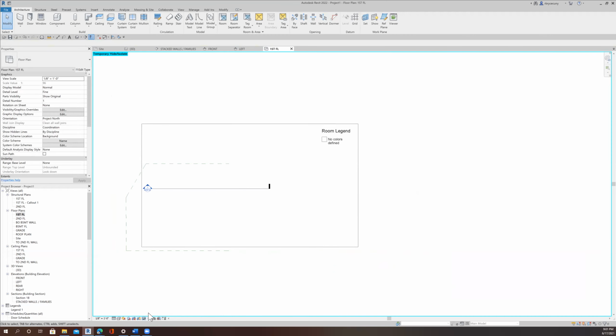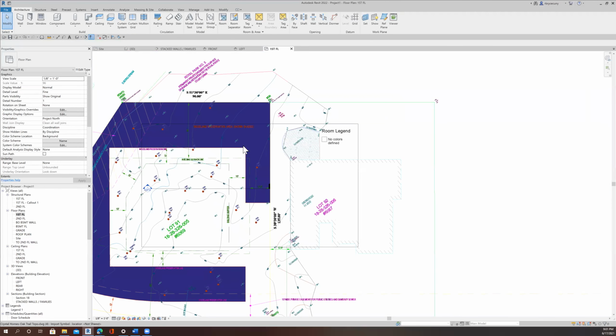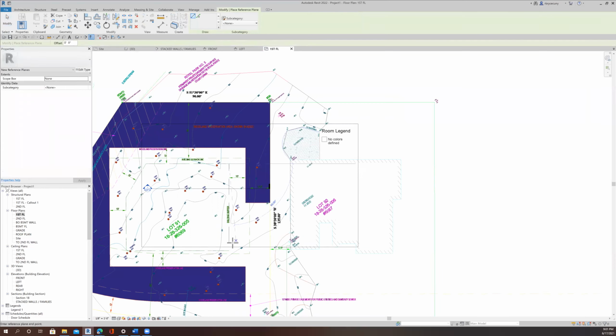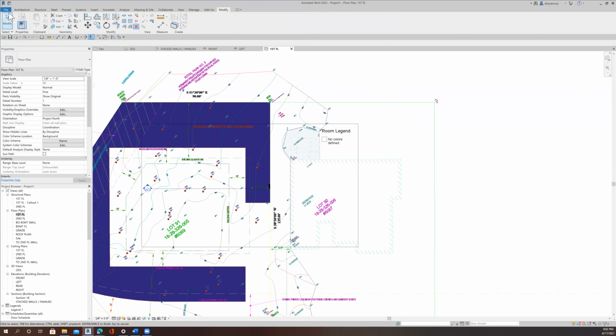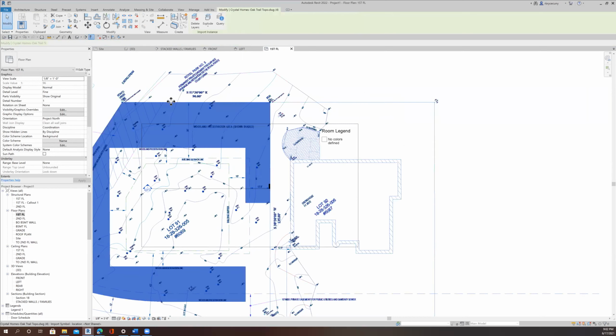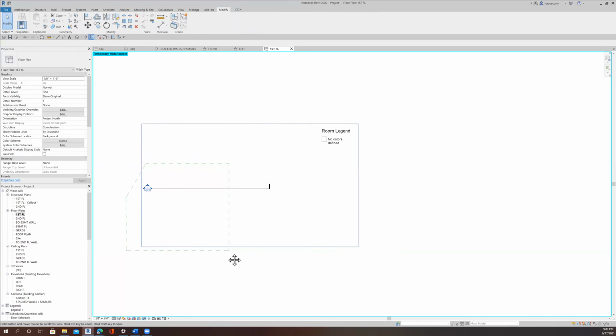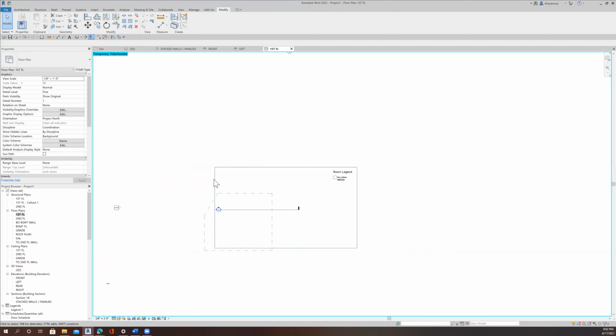All right, so I'm taking a little time here to set it up correctly so that I don't have any mistakes later on down the road. But I want my reference plane. I can see that the names are there, or the click to names are there. So I'm going to say okay to that. And that's definitely there. I'll click back on this site again. And back to here, hide the element. Okay, so now I have my reference planes in there.